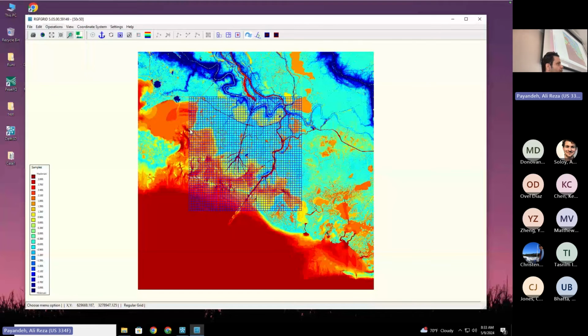I will have a lateral boundary on the west. I don't want it to be on the land. I don't want it to touch any land. Let's move it a little to the west. And we do that by adjusting the coordinate of the lower left corner. So I hover over again here. I just need to adjust the X coordinate, right?